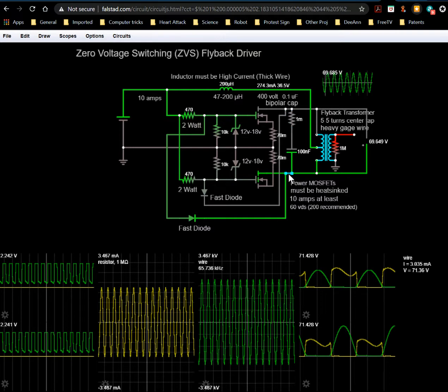So that gives us 71 volts, because remember, this isn't 0 volts. This capacitor has like 69 volts across it. Again, more like 2 times 1.414, right? That's where that extra voltage is coming from. The voltage across the actual capacitor is never more than 69 volts. So again, I think it really is 2 times the input voltage times 1.414. I think that's why it's approximately 3 times. I don't think it's because of pi.